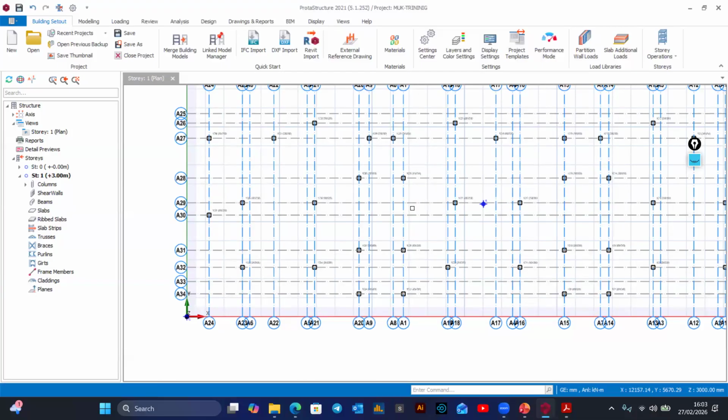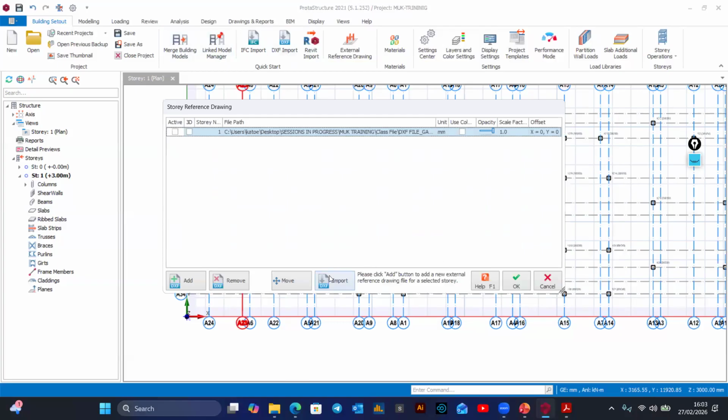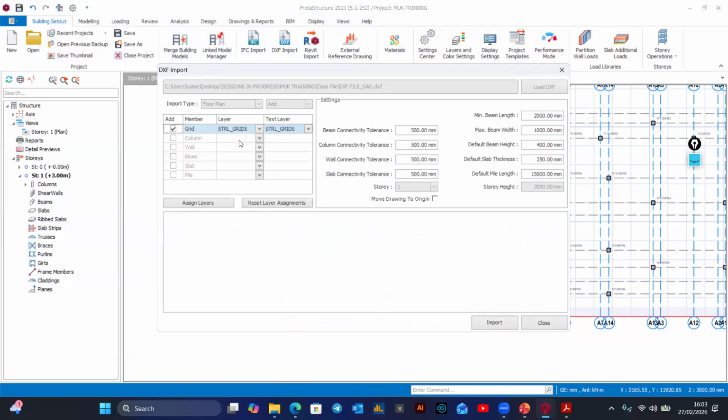That's why if I had another layer called beams, because beams also have closed loops, right? So if when I was importing here, instead of choosing column, I chose maybe structural beams, it was going to extrude beams instead of columns. You get it? So I don't know, but that is how it is.